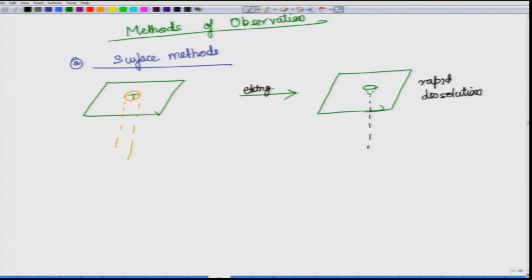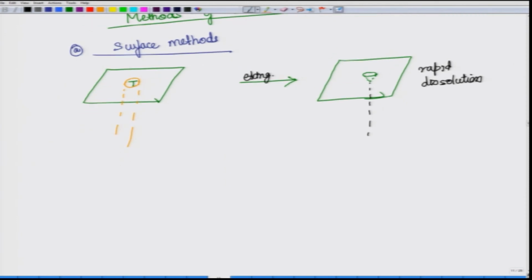This is for edge dislocation; for screw dislocation it will be different. Not only the cylindrical kind, you can also see the effect of facetting. Even for an edge dislocation, in many cases, because of the crystalline nature of the material, you may see this kind of faceted structure, and what it implies is that below this is the dislocation line.